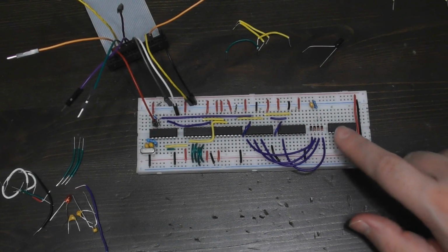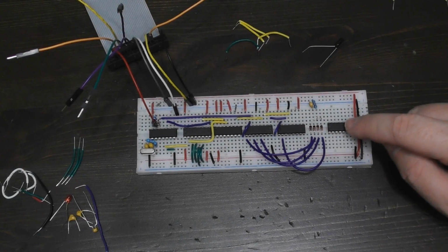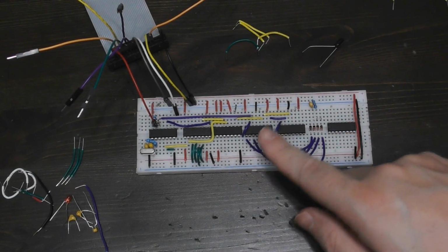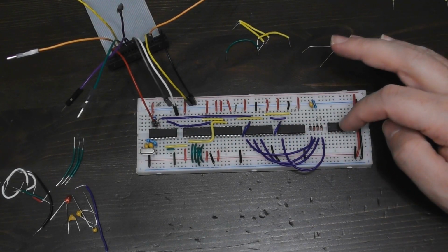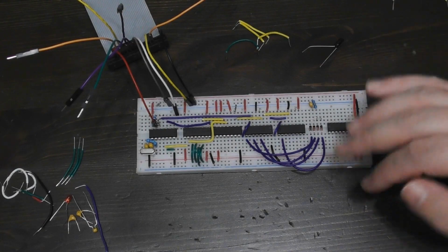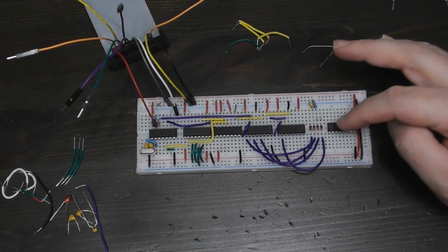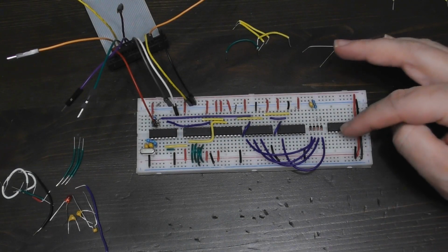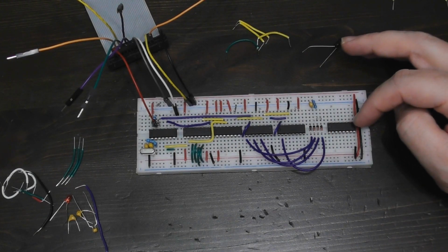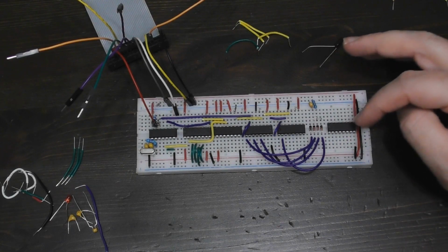And after that happens, the terminal count signal on this counter will go high for 1 pulse, one reconstructed clock tick. That's something the CPU will be able to notice, either through an interrupt or just by polling for it, and when that happens, the CPU can read that data. At the same time, this counter is a 4-bit counter, so it's going to reset and count for another 16 ticks.